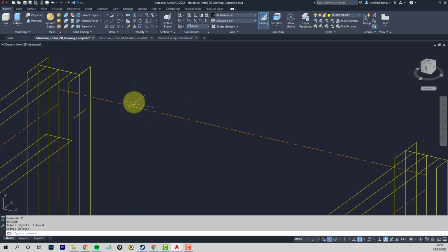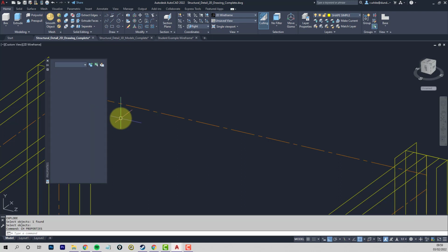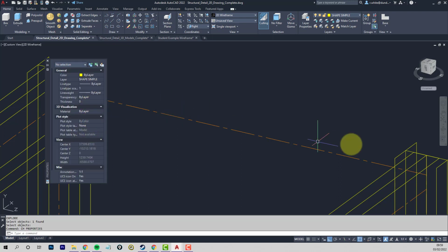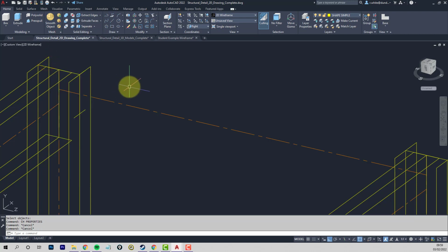Okay, we're going to use the change command, but using it from the keyboard instead, and that gives us an option to change the thickness by picking on screen. When you use this panel, you can't pick the distance you want to use. But if you use -CH, that forces the command to stay in the command prompt. So the minus makes the command stay down here.